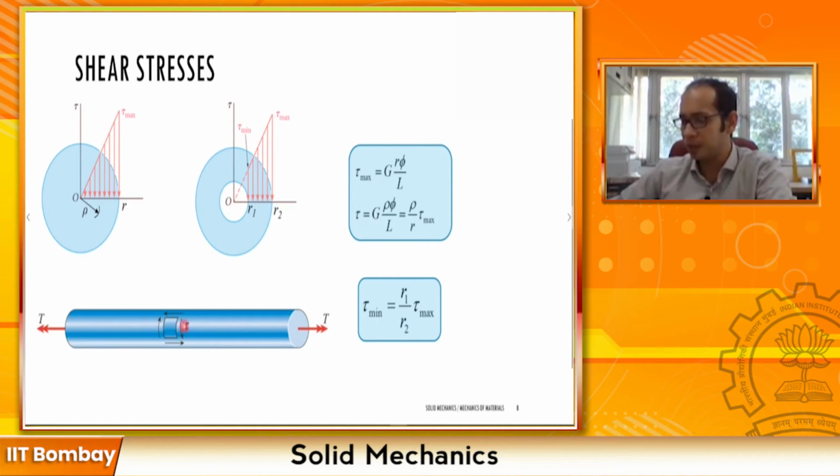So that means that if I have this tau over here, to balance that one, because summation of Fy equals 0, remember equilibrium, I must have a tau over here, right? Now this tau and this tau, if you take a small block of an element, it forms that in equilibrium, and it gives rise to that couple. To balance that, I must have a tau on top and a tau on the bottom over here, right? So now the interesting thing is, since we are looking at an exterior element, all these taus are nothing but your tau max, because we are looking at the outside periphery over here, right?